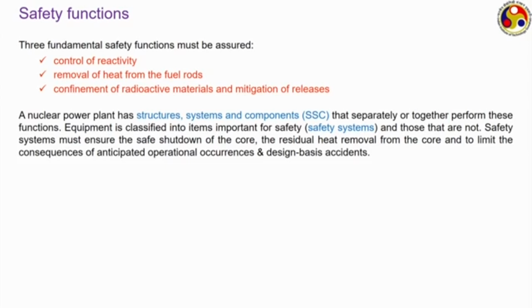To attain all these fundamental safety features, the structures, systems and components, which are together known as SSC, act separately or together, and accordingly the equipment is classified based on the importance to safety, or rather I should say the equipment which is required to ensure safety, that is which has relation with any of these three safety functions, and equipment which is not at all related to safety. Safety systems must ensure the safe shutdown of the core, residual heat removal from the core, and that the consequences of anticipated operational occurrences and design basis accidents are taken care of.